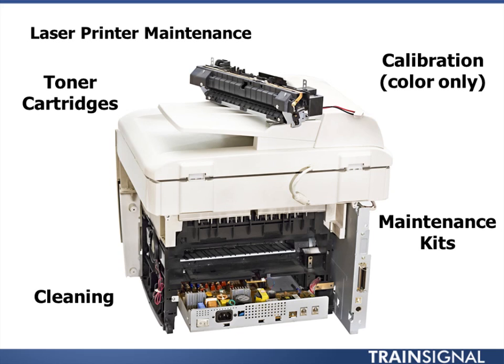Okay, if you're having problems with the charging roller or the corona wire or the cleaning blade, and these are all things that are contained within the toner cartridge, not just the toner itself. Now, even if those don't go bad, and very often those don't go bad, because these toner cartridges are designed to last for at least as long as the amount of toner that's inside, the actual ink itself, the actual little iron particles.